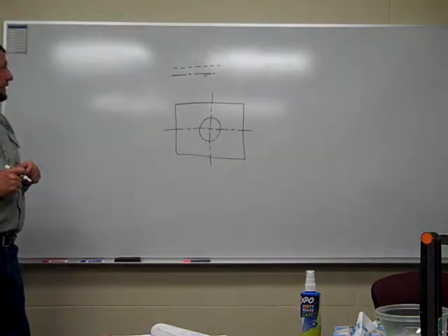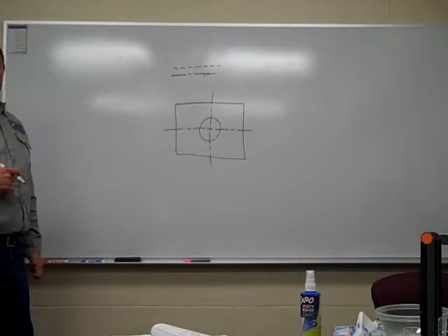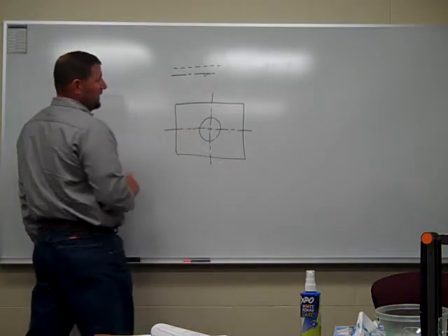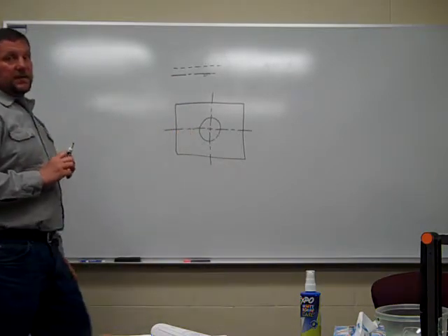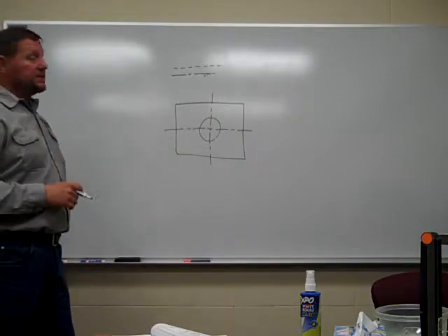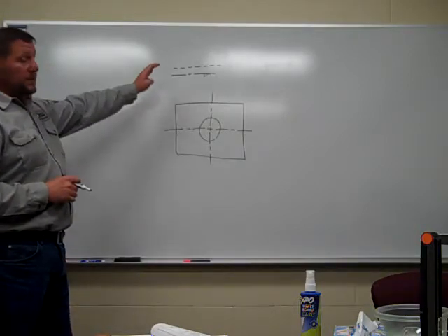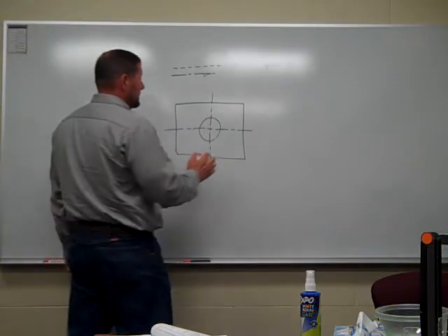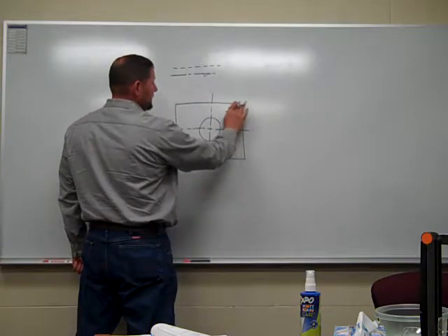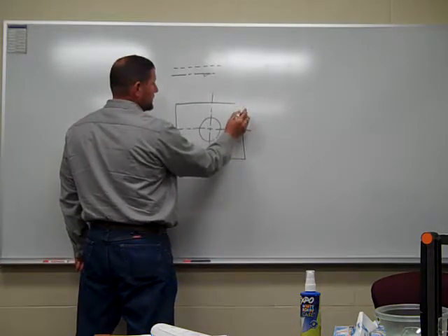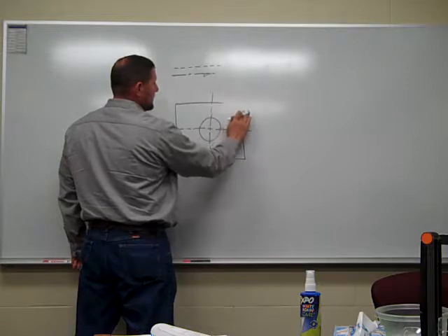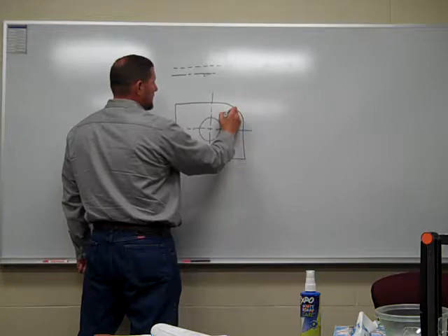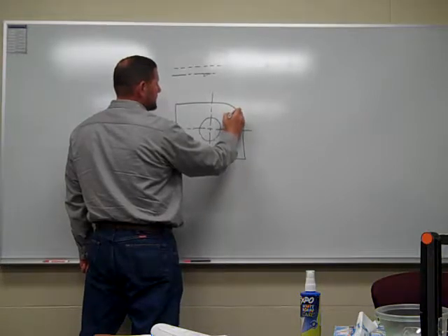They could be anywhere, and just about any length. As you can see, the dashes are a little bit different than the hidden line. Get them memorized, because you're going to be tested on this, and as you get through this class, or this competency, you're going to go through a lot of center lines, a lot of hidden lines. It can also show the center of a circle in that plate. Let's say if I put an arc on this, a radius on here, they can also be used to depict the center of that arc.